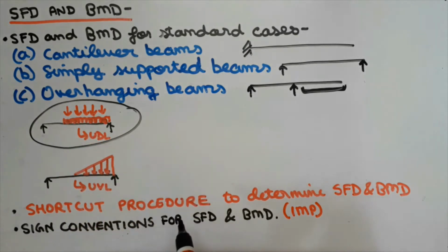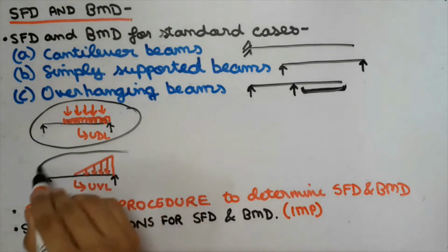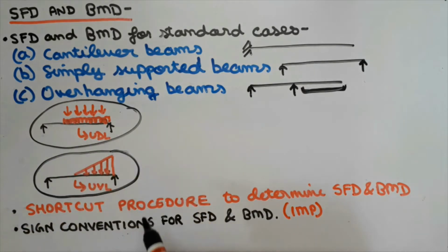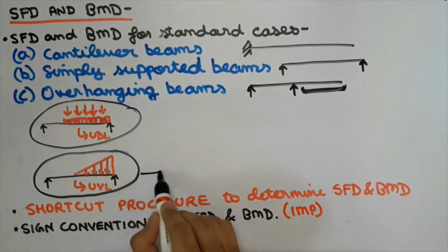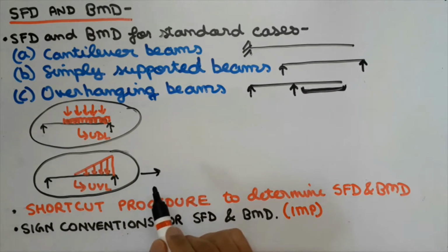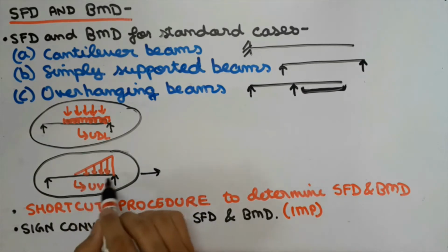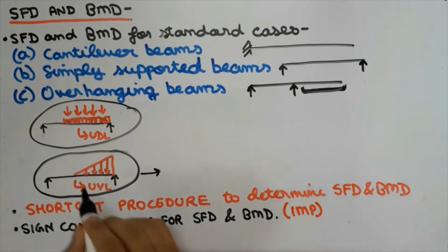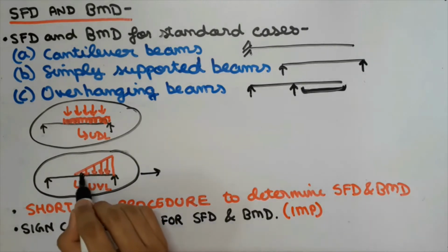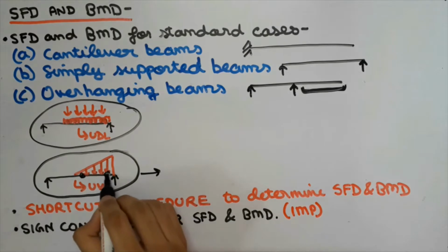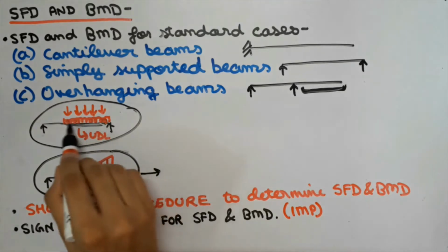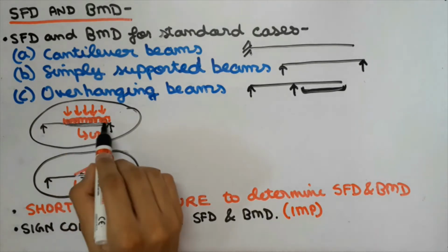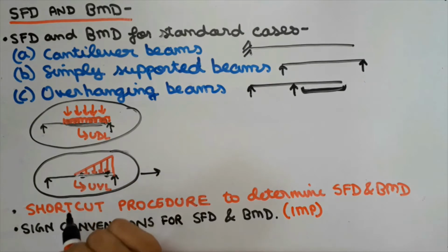forces being applied. And similarly, UVL is completely different from UDL. UVL is uniformly varying load, in which the forces acting on the part of the load which are on the beam will be different at each point. That is, you will experience a different force over here and a different amount of force will be experienced here. On this whole part you will experience different amount of forces. But in UDL, on each part of this load you will experience the same amount of force.